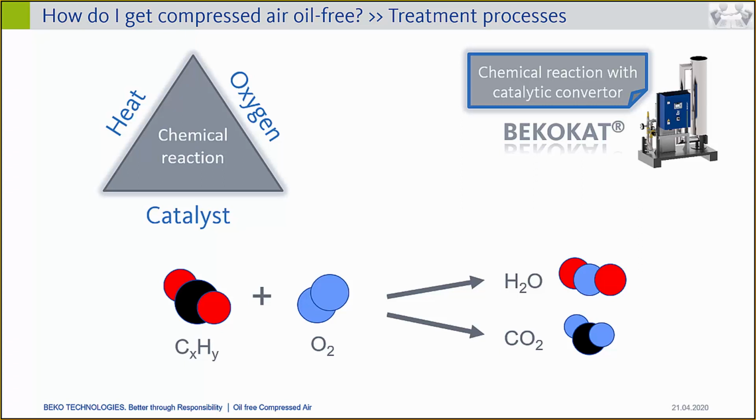The carbon dioxide is, just from the name, one negative effect we do not want to have in our environment. But there are no worries in that situation, because the carbon dioxide being created is based only on the amount of oil which is entering the treatment system. And you may know that the amount of oil vapor is approximately 1,000 times less than the amount of water vapor which enters the compressed air system. We will also see a few more numbers on a couple of slides later.